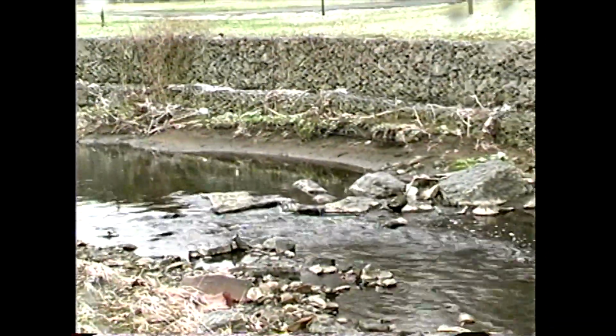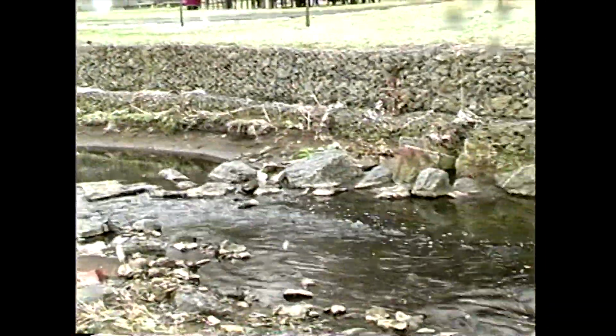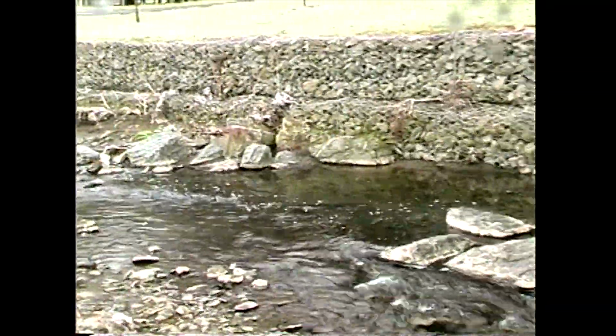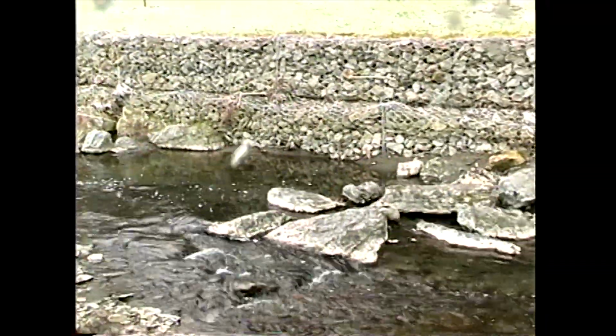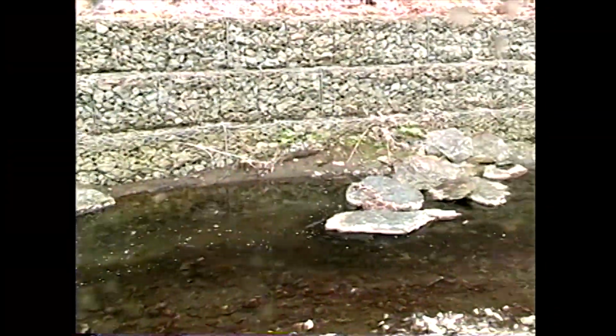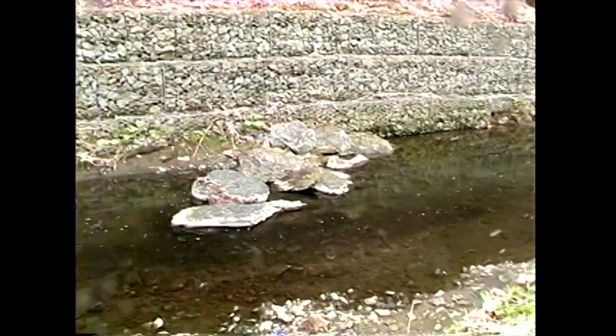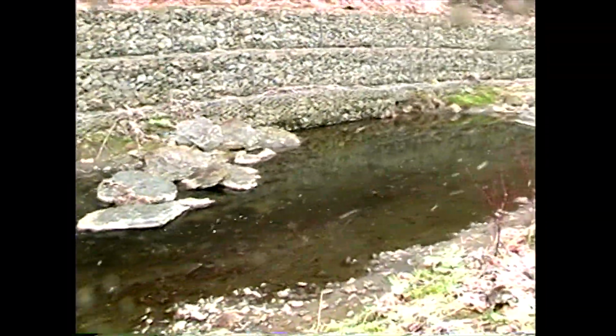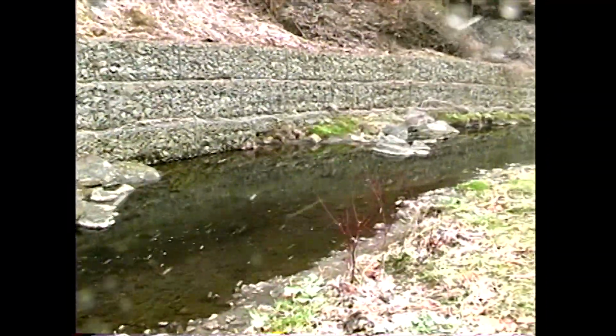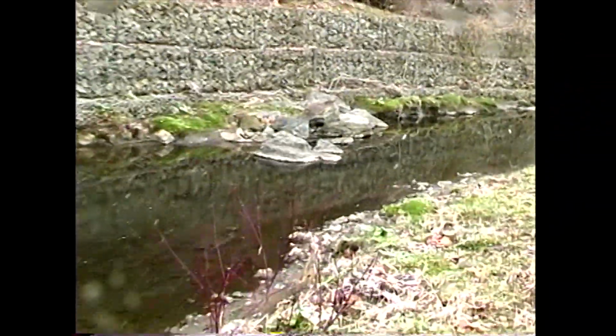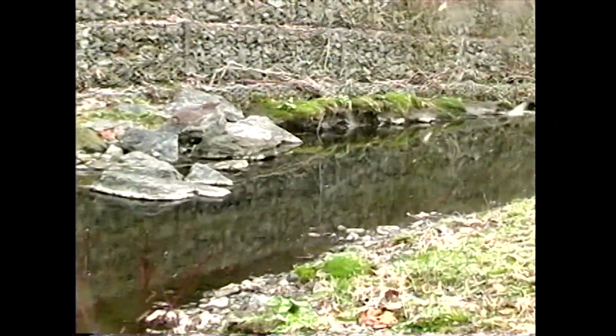The water deflects off that and flows off the tip of the second rock vein, and so on and so forth as it's moving around the meander. This keeps the water during all flow events mainly in the center of the channel, which keeps the erosive force away from the outer bend of the stream, where we're trying to protect the gabions.